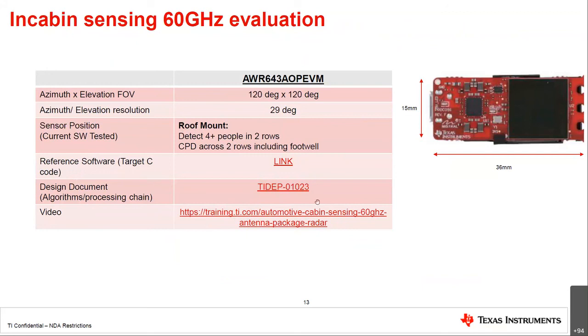And again, for anyone who is looking at radar sensors but is not specifically interested in in-cabin sensing applications, the same link will also take you to our general software repository that has other application software such as people detection for HVAC applications, gesture detection for both infotainment as well as general consumer electronics applications, and heart rate monitoring. Again, underlying all of these technologies is the same kind of sensor, the 6843 AOP sensor, which enables you to detect motion with a high degree of fidelity as well as localize that motion.